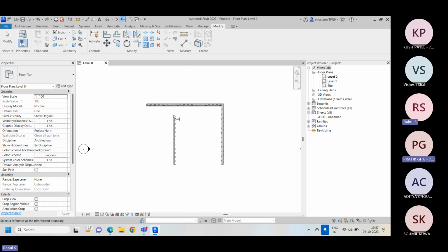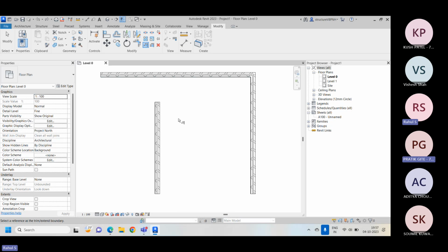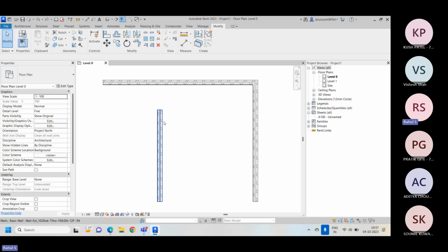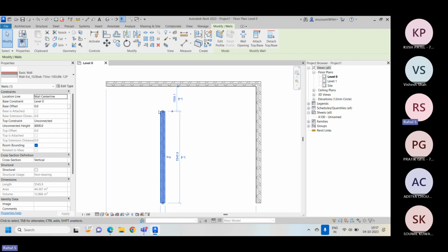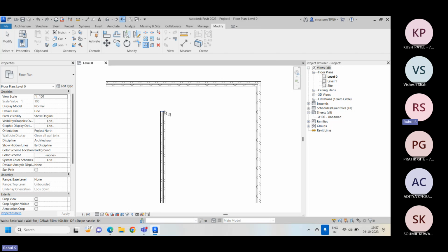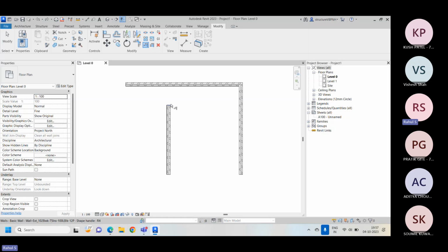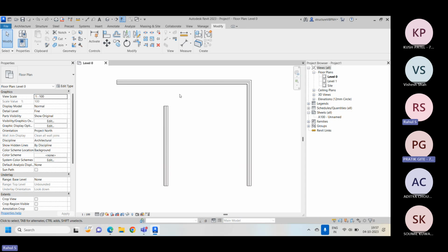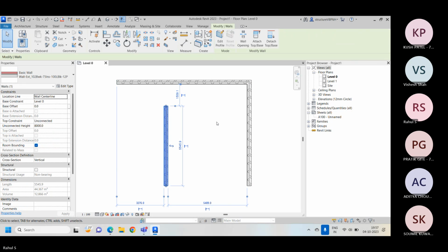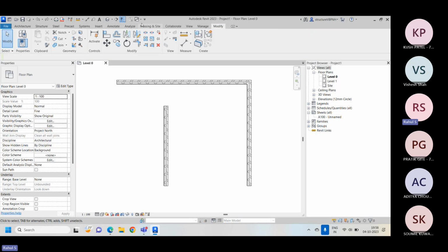So what do you need to do? First, select the object. What do you want to do? I want to connect this surface to this edge. Now I have only a single object, right? So I will use the extend single element command, because I want to extend it. I will select this. What do you want to extend? This surface, with respect to what? This surface, and select it. Okay, you understand that command. Clear? Yes, sir. Okay, great.